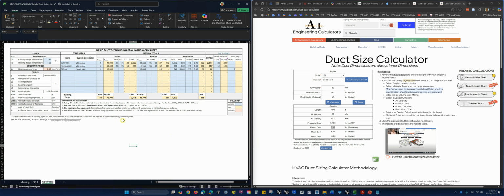Okay, is there anything else? One other thing I would say is that these totals down here are perhaps not useful in this case. What I would probably do is say, okay, this is a VAV system with a boiler. Oh no, it's an air source heat pump, but it could be the same air source heat pump for both. So maybe I'll add these two together and look for a piece of equipment that delivers that. Or maybe I make this one not an air source heat pump. Maybe this is a condensing boiler, and I just want one place with this condensing boiler, and a chiller or something like that for cooling. Then I would look at these individual outputs for each zone and size the equipment.